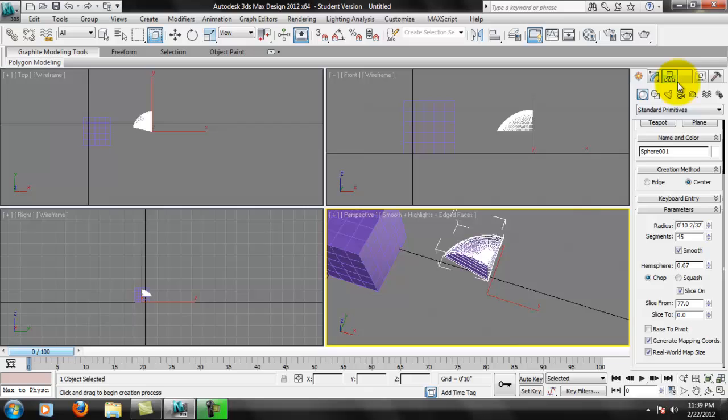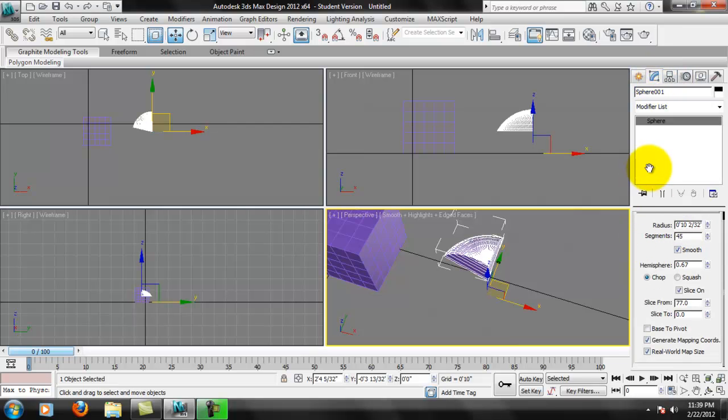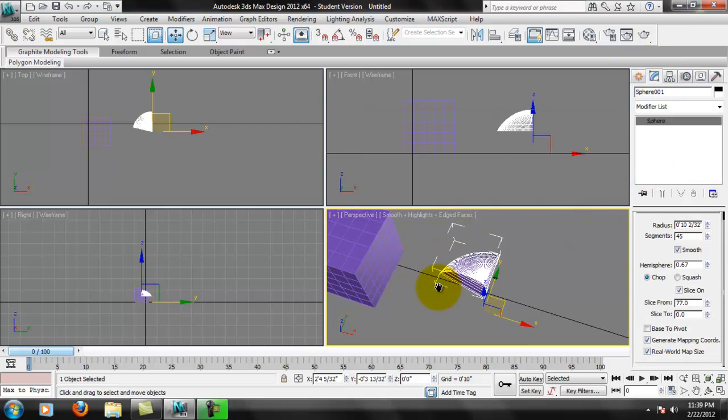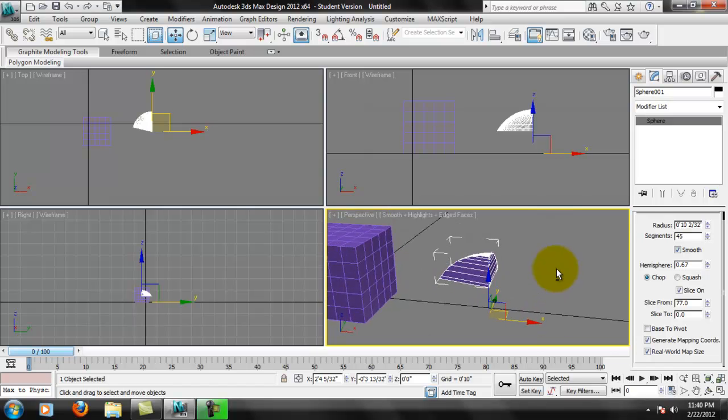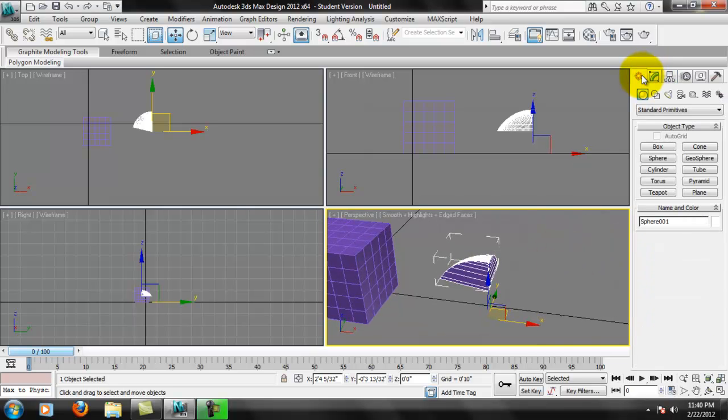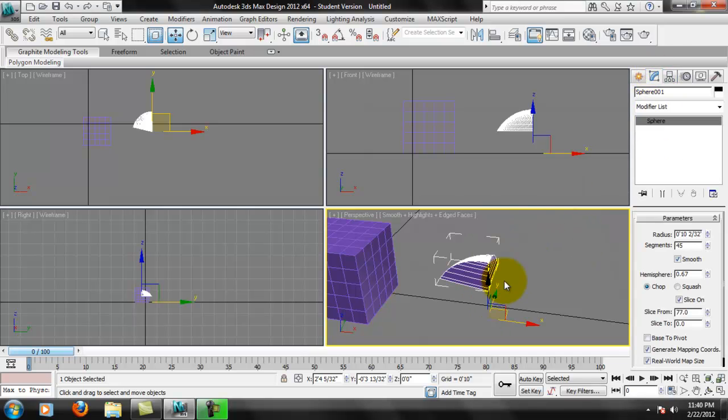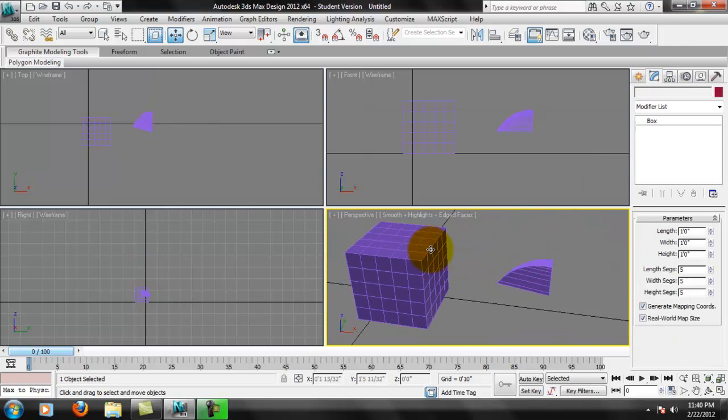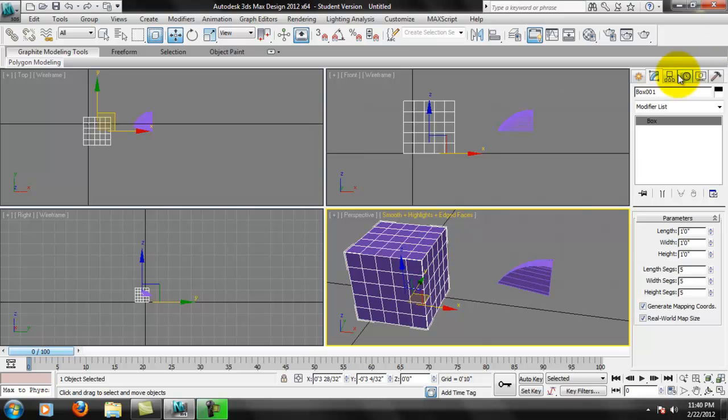So that is basically the parameters, even under the Modify tab here. Notice I didn't actually switch to Modify, so I should get slapped on the hand for that. But under the Modify, same idea, same tools. If I go back to the new tab, you'll notice that's gone because I would have to actually create a new sphere. So to do any modification after the fact, like to do any modification to this box, you have to select the box, go to the Modification tab, which is the second tab over, and change your parameters here.